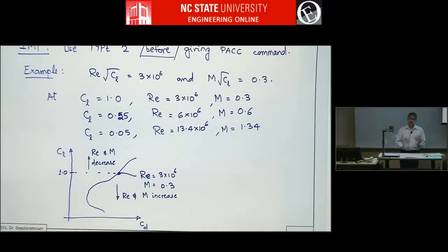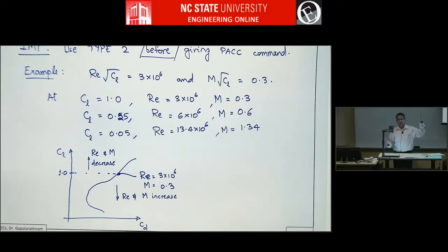So this is all built into that Newton iteration that we talked about. You know, X-foil has that viscous inviscid interaction, so it's iterating, right? While it's iterating, as the lift coefficient changes, it will automatically change Reynolds number, which is, think about it, such a convenient thing. If you're designing airfoils for aircraft, without this it would be a real pain because you can generate a polar, but that polar is valid only at one point. Then you have to generate another polar for another point, and then you have to look at a family of polars. Now this automatically takes all that into account.